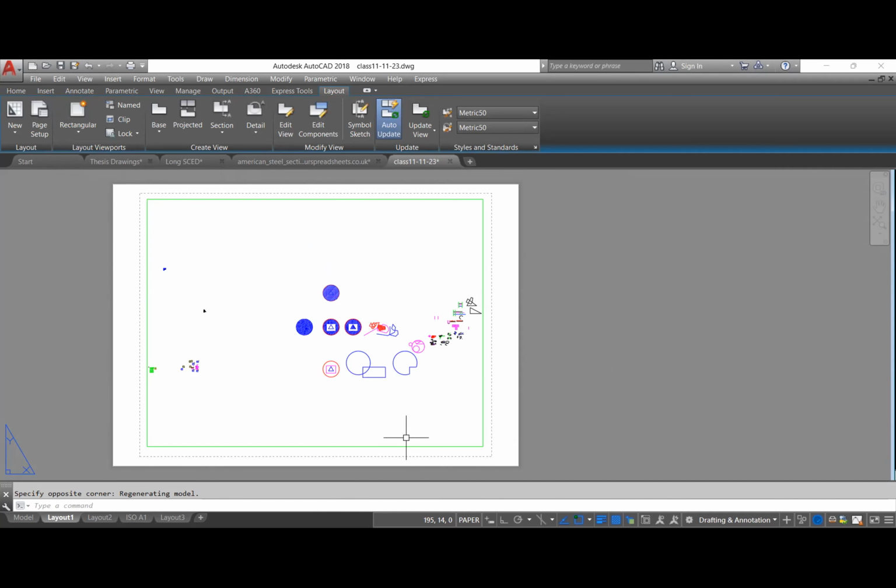So that you can always manipulate that layer. Sometimes you don't want the viewport to be plotted, or printed. So you would want to maybe do VP freeze or maybe plot freeze or whatever, and you would want to take that opportunity. Now let's click on the viewport and then delete it.